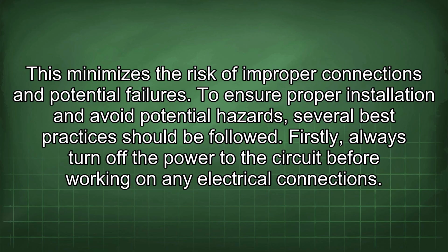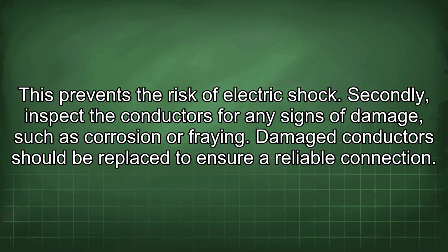To ensure proper installation and avoid potential hazards, several best practices should be followed. Firstly, always turn off the power to the circuit before working on any electrical connections. This prevents the risk of electric shock. Secondly, inspect the conductors for any signs of damage such as corrosion or fraying. Damaged conductors should be replaced to ensure a reliable connection.